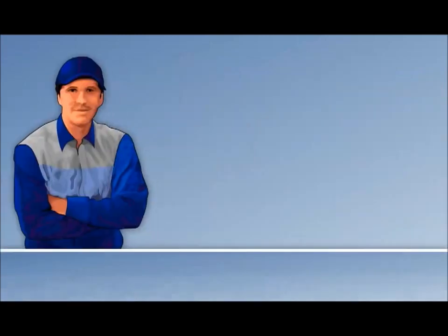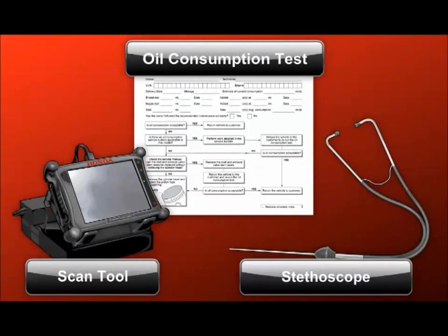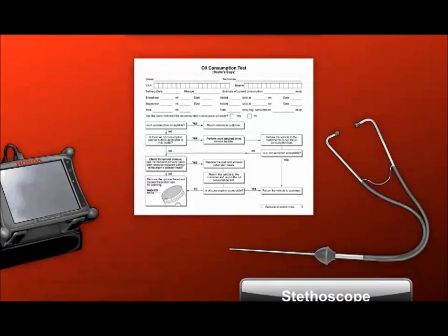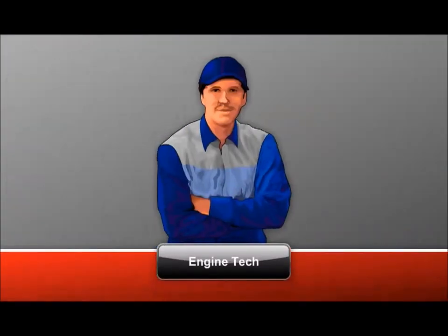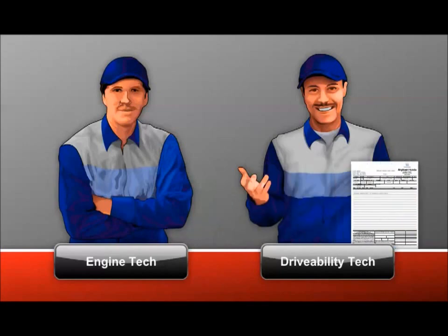Because of this, when technicians see drivability problems, they must decide if they are dealing with a mechanical fault or a fuel and emissions fault. This module provides several checks to help separate drivability problems from engine mechanical problems, but not all faults can be divided using these checks. Technicians who cannot troubleshoot both systems should check over the engine mechanical system, and if they find no mechanical fault, pass the car on to a knowledgeable drivability technician who can correctly evaluate the fuel system.